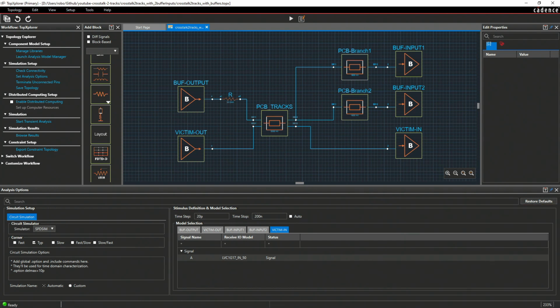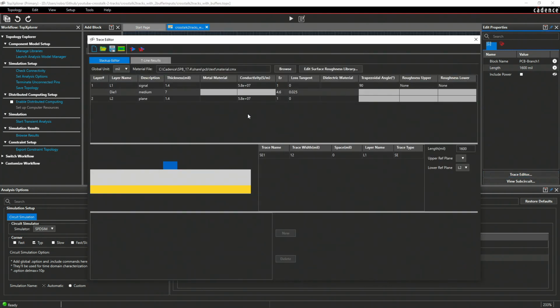There is something else I would like to show you in this video, and it's about the length of these tracks. So what I'm going to do, I'm going to remove all our improvements. So I'm going to delete this resistor. I'm going to connect this back, and I'm going to use the two-layer PCB again. But instead of using these very long tracks, we are going to make them shorter.